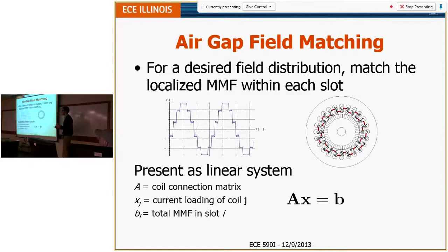So that's the same as reconfiguring the winding. So in essence, you could create a machine like a transmission where you vary torque speed curves dynamically on the fly. And it seems to me an electric car, for instance, would have application. Yeah, that's true, but in an electric vehicle you're limited by your mechanical structure, which is always going to kind of get in the way.